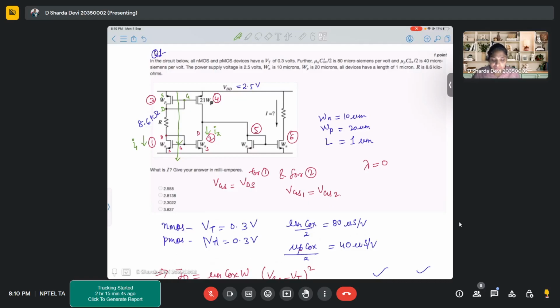Actually, in that circuit, the VGS was not different. I mean, it was different. VG was same, and in the source there was one resistor which had been implemented, which was changing the VGS. Yes, so there you cannot use this concept. Here we are simply saying that VGS is same. So many things become very easy because of this VGS equal. Now the moment VGS will change, definitely your currents will not stay the same. The currents will be affected. So that way it will change your analysis.